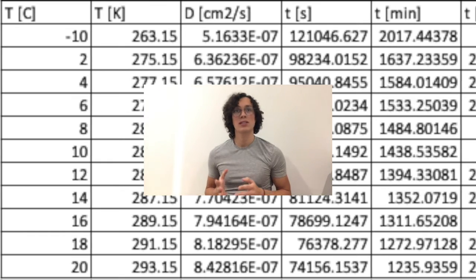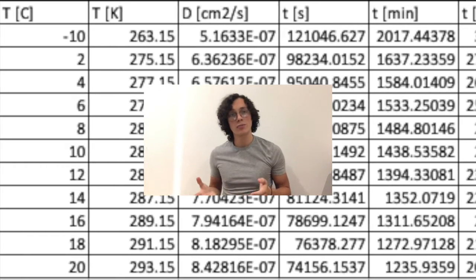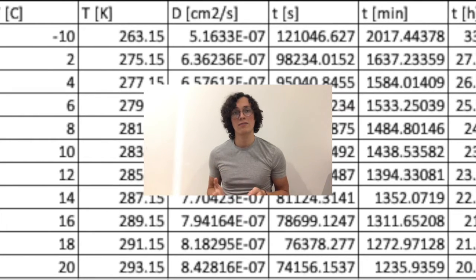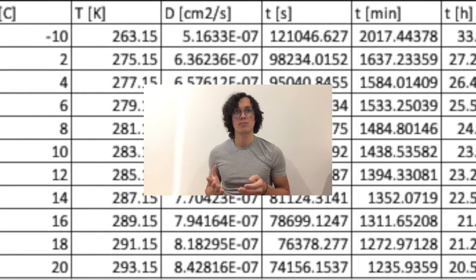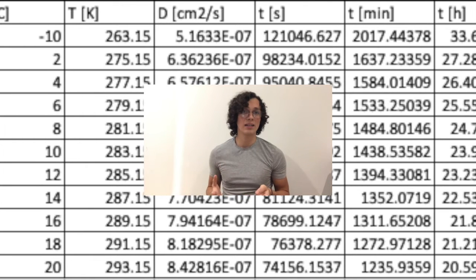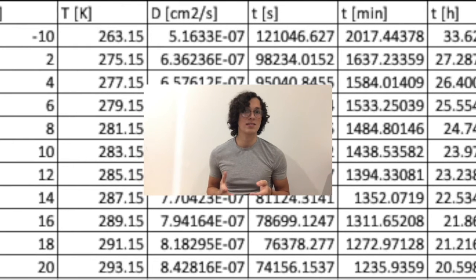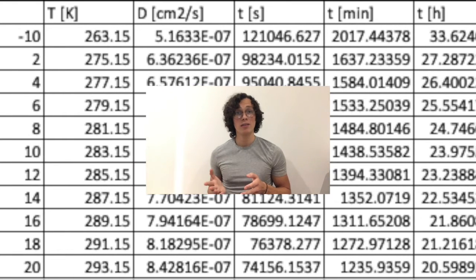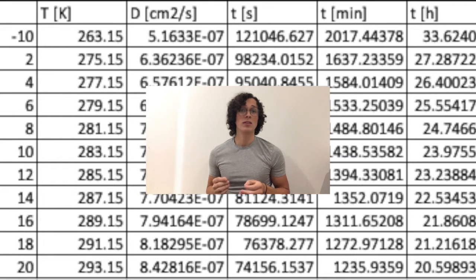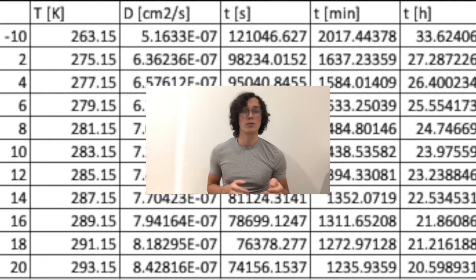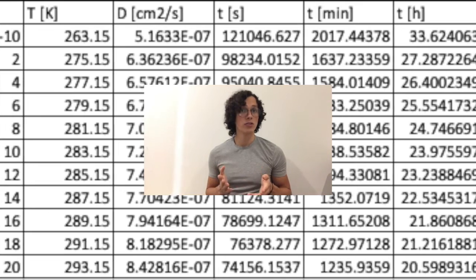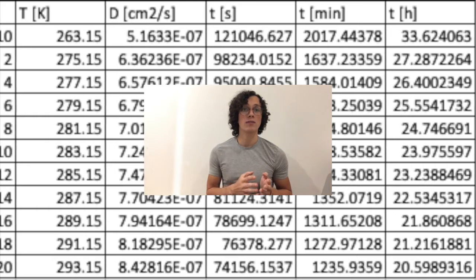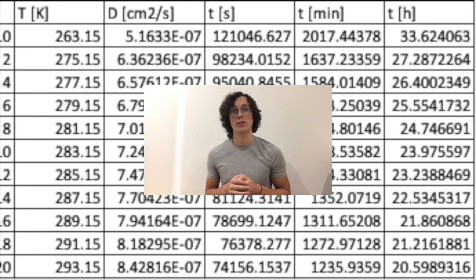As conclusions, it is possible to say that results are somewhat viable, as this model is very limited and it would not be used in a real-life oxygen concentrator, in which sieve beds involve many materials, many layers, and different compositions of gases, but it still communicates to us the behavior of air in zeolite beads, and it could communicate to us the behavior of different gases through this material. It also shows that lower temperatures are favorable in order for the longer functioning of our oxygen concentrator.